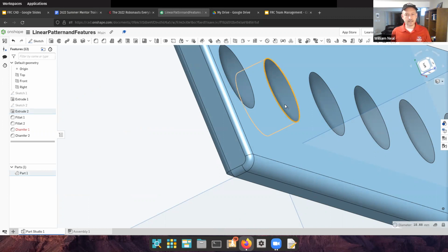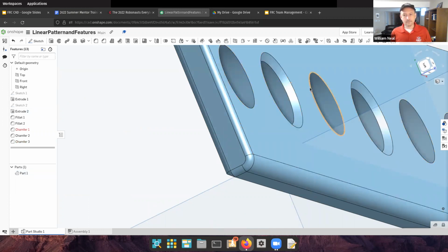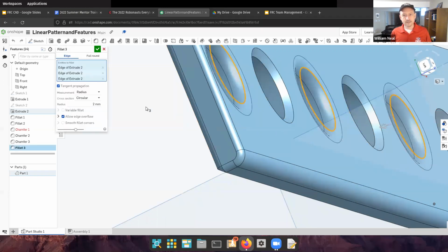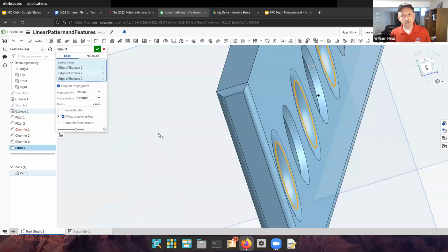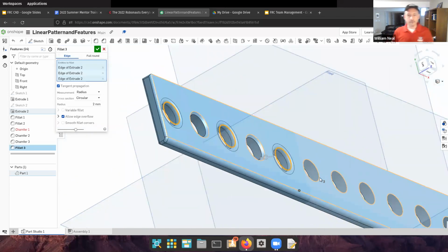Here, I've selected a circle. What will it allow me to do? There, I tried a chamfer, that worked. Try this circle, select this one, and we'll try, oh, it allowed for 2 chamfers there. Okay, I forgot to come out of the feature. Now I'm going to select a few others. Holding down Shift, I can select a few features here, and let's just make those fillets. There, so you see some of them are straight edged and some of them are rounded. And I can do this all throughout my model.